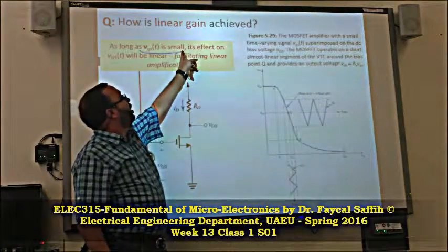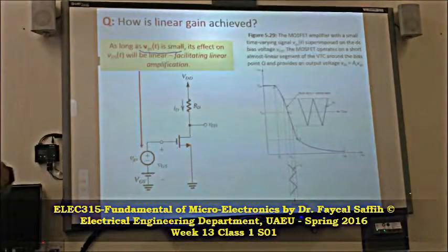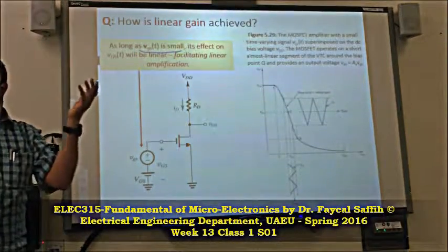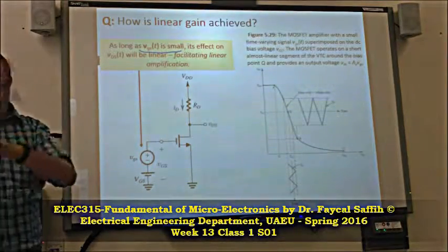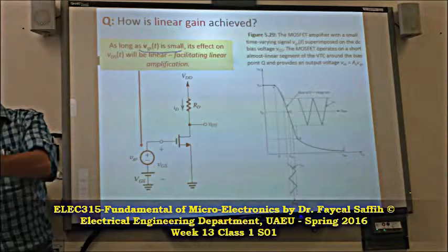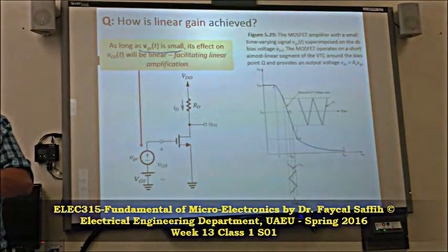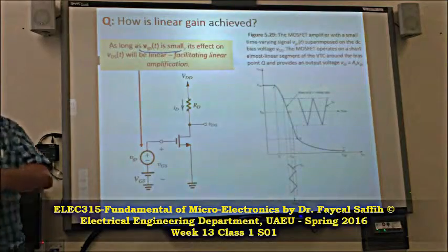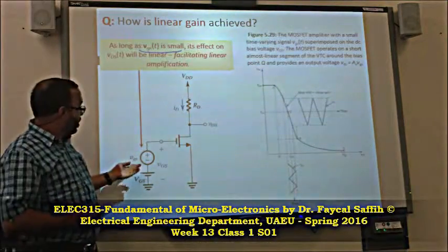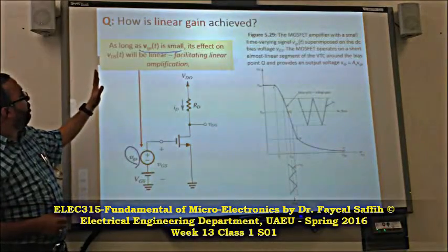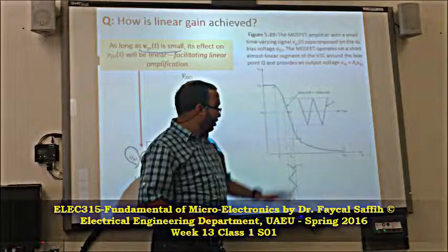The condition to make this linearization is that VGS has to be small. We'll talk about how small. If you remember, there's one slide where we gave the estimation of VGS, and we said that VGS is less than 2 overdrives. You can go back to that slide, but we can review that. As long as this VGS is small enough, this can be considered a line.